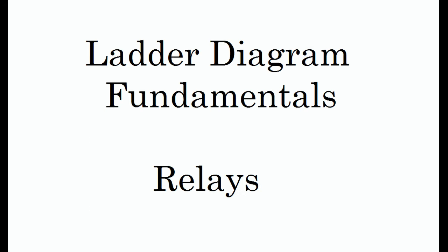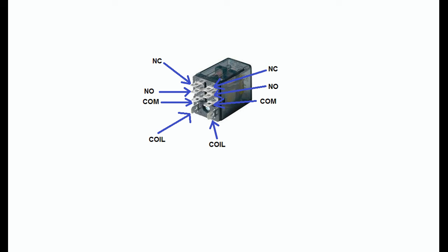Relays. Early electrical control systems were composed of mainly relays and switches. Switches are familiar devices, but relays may not be so familiar. Therefore, before continuing our discussion of machine control ladder diagramming, a brief discussion of relay fundamentals may be beneficial. A simplified drawing of a relay with one contact set is shown in the figure. Note that this is a cutaway, cross-section view of the relay.